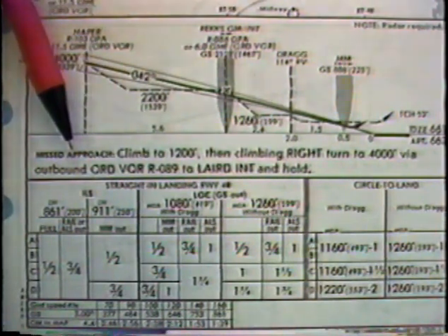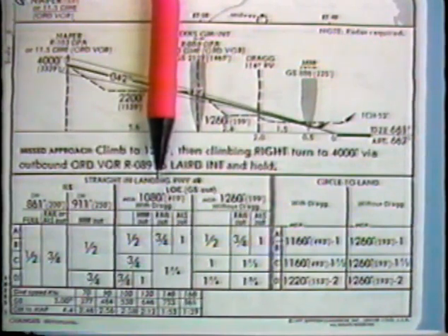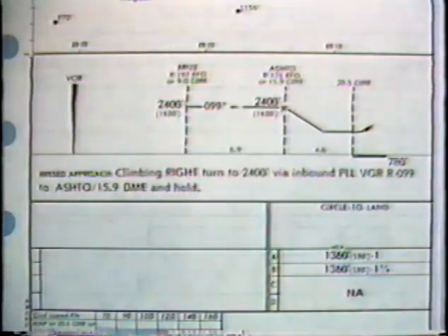If the runway is seen, a landing can be made. A straight-in landing is a landing on the runway referred to in the approach name. Landing on other than runway 4 right constitutes a circle to land maneuver and requires the use of circling minimums, even if no actual circling is done to line up with the desired runway. If an approach name does not specify any runway, as in the Rochelle, Illinois VOR-A approach, no straight-in minimums are shown.